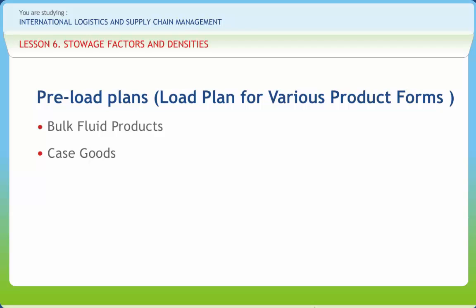Heavy cases should always be given bottom stow with the lighter cases on top. If the contents of the case are pilferable, then they should be loaded onto a lock-up stow and tallied in and tallied out. Cargo in drums is not unusual and can be varied by way of chemicals, oils, paints, dyes, and even sheep dip. Drums may differ in size, but a 50-gallon drum is probably the most common size for oils and is often used for own ships' stores of lubricating or diesel oil.